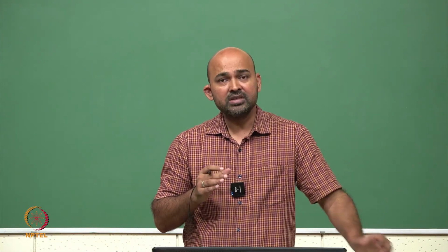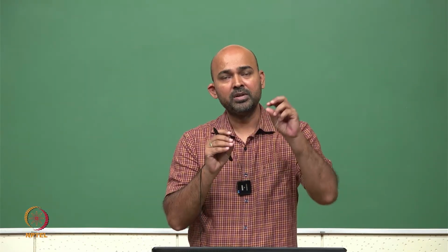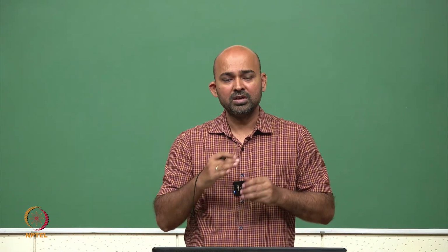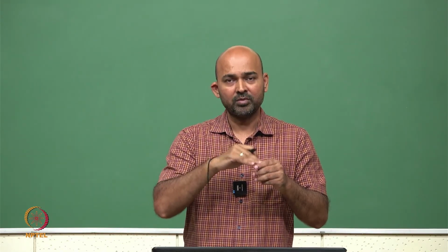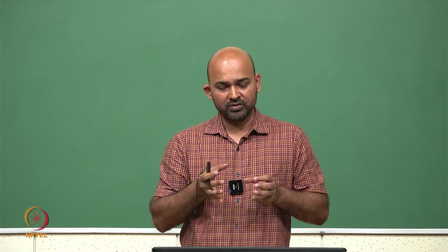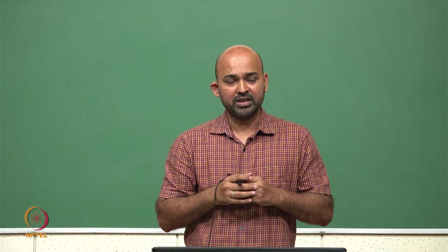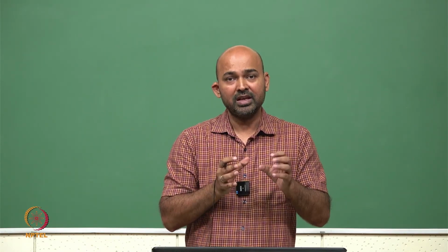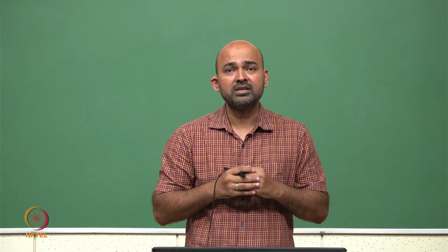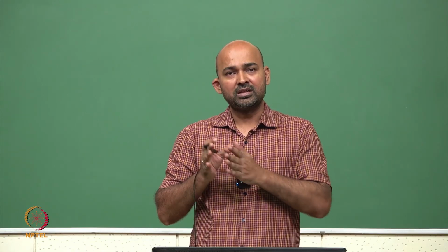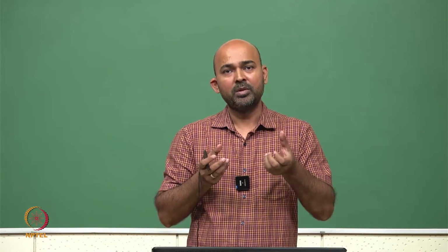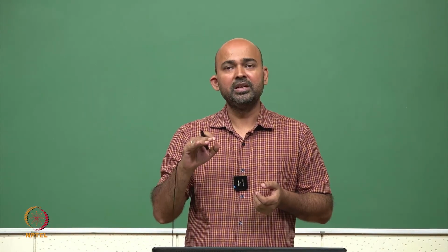The second is we still have full swing. The output is completely charged to VDD, and when this is discharged, it is completely discharged to ground. If we have rail to rail swing from low to high and completely high to low, then we have very good noise margins. So that is still there in dynamic logic gates, despite the smaller number of transistors. Still a ratio-less design, because the output in the steady state condition does not depend on the ratio of pull up network or pull down network. This is completely 0 or 1.